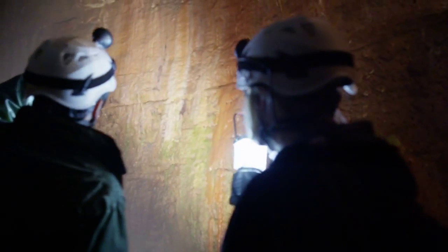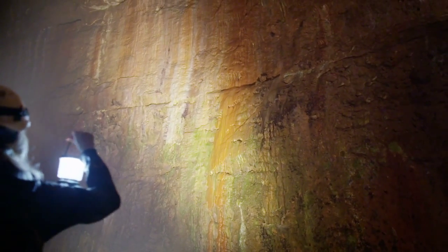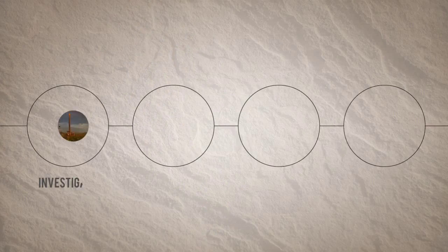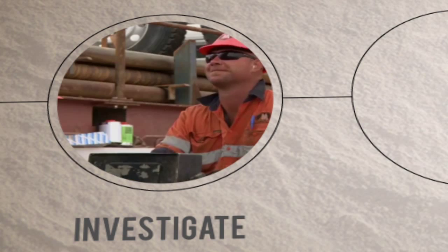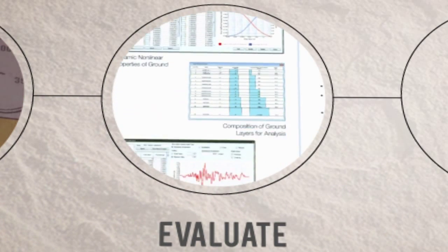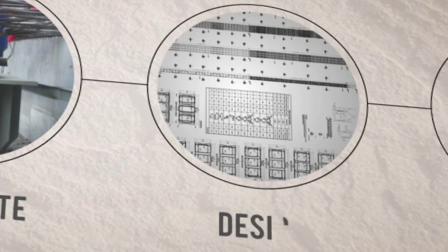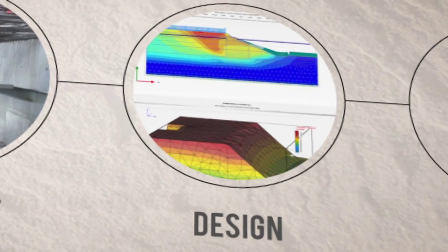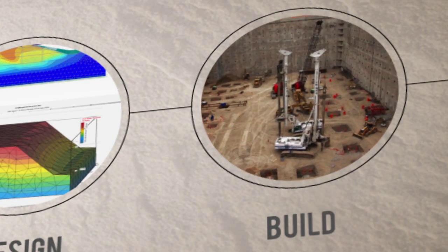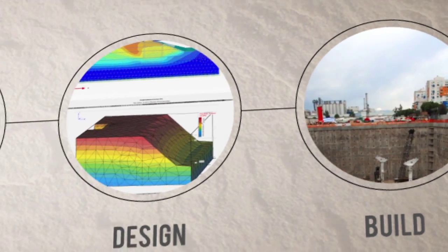Geotechnical engineers use fundamental principles of soil and rock mechanics to investigate subsurface conditions. This allows them to evaluate and design activities such as the stability of natural slopes and man-made soil deposits, earthworks with cuts and fills, shallow and deep foundations, dams, retaining walls, tunnels, and many other works directly interacting with the subsoil and water.